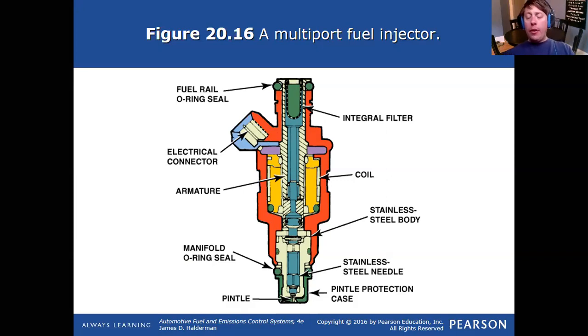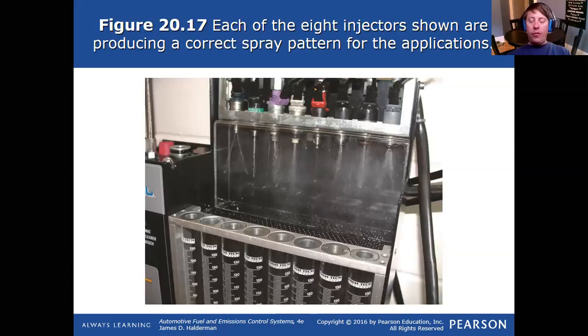And so the computer then has to compensate by increasing the pulse width of that injector to spray even more fuel out in order to satisfy the oxygen sensors, fuel trims, etc. And you'll end up with engines that have a misfire, engines that have poor fuel economy, have elevated overall tailpipe emissions.